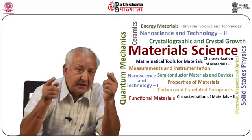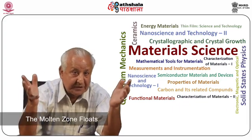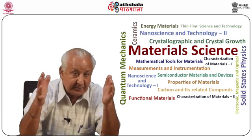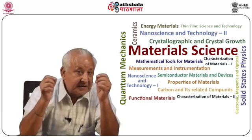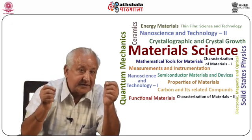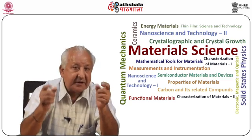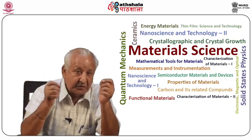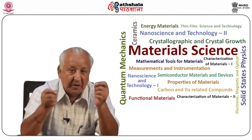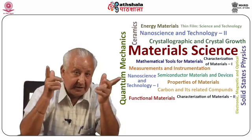This technique does not require any crucible. The molten zone floats below two solid parts of the rod held in place by surface tension. Since it does not require a retaining crucible, the technique has the advantage that possible contamination from the container is avoided. It is used for the growth of silicon, which is the only material grown on a very large scale, around 1,000 tons per year.